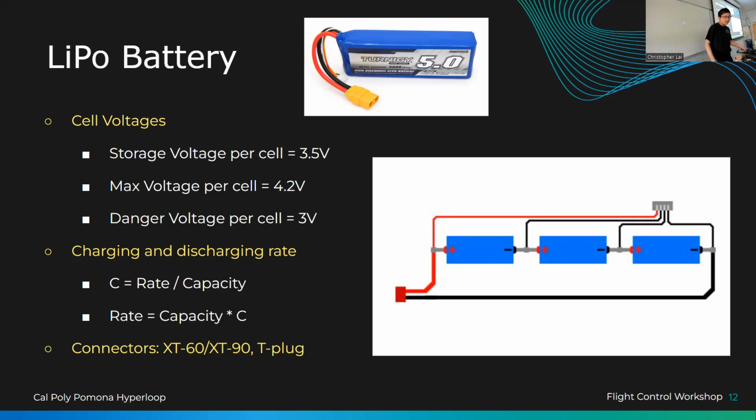And for tinier little drones like the Tello, they actually do use LiPo batteries, but they come in different packages. It's usually coming in tiny little ones like this. You pass it around, it's not gonna blow up on you. And these batteries are great because they're small, they're compact, but if I have a smaller battery, what am I losing out on? Capacity, yes. So these only have 1,100 milliamp hours of capacity. What else?